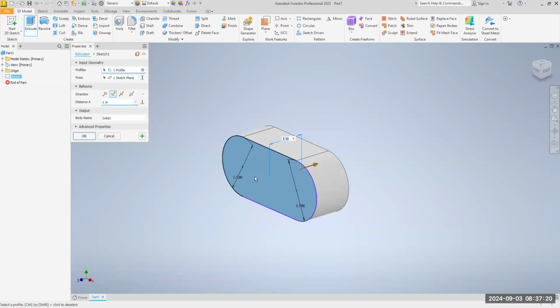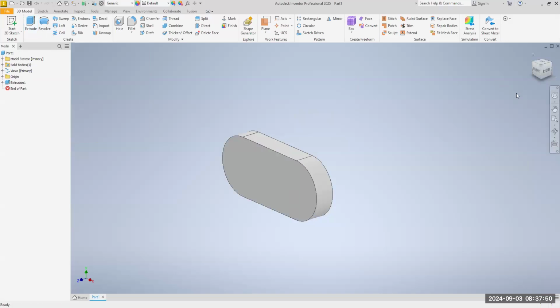You'll learn more about this later when we're doing some machining. The distance now, I want to make 0.5. I hope I didn't confuse you about the machining. That comes later, but I want the top of my surface to be Z0, right? Z0. So you look at this axis, here's the Z-axis, that points to origin. The origin will be right on top of the piece here. Select OK.